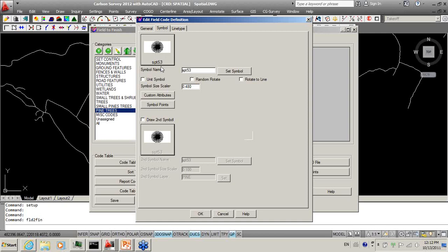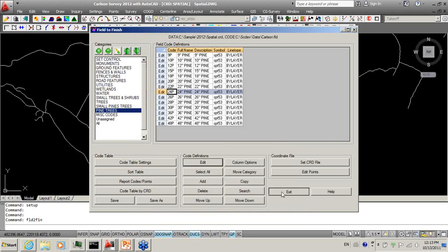So one use of this would be to have a typical 2D symbol, and then have the second symbol be your 3D symbol. And also the special code for sizing symbols has some improvements where you can size the XY separately from the Z and other things. So, okay.